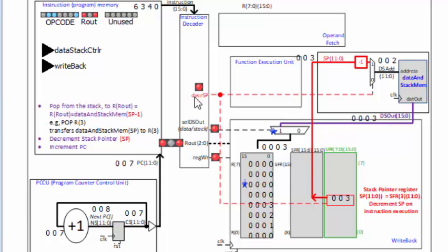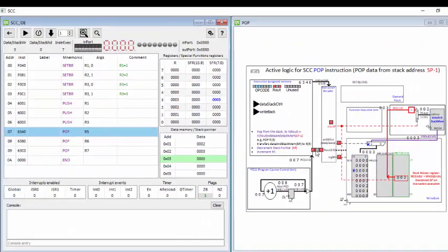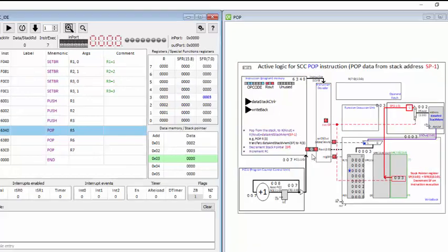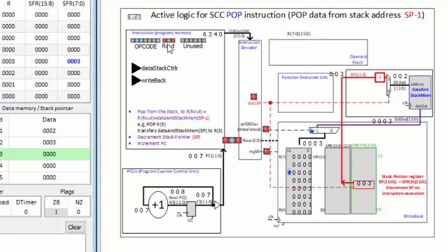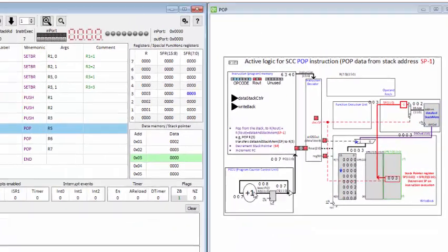Notice that the instruction decoder now has decrement stack pointer asserted because it will now decrement the value 3 to 2. The stack manages the current address and the pointer. Also select data and stack out is a signal that's asserted because it has to select the path from data and stack through in the write back block. And the register that's been written to is register 5, which is the destination in the instruction, and it's shown by the star here. And register write is also asserted. So there are a different set of signals in the instruction decoder that are asserted. The 100 for the destination register is part of the instruction up here, and the opcode is different from the previous. And again, the program counter is just incrementing.